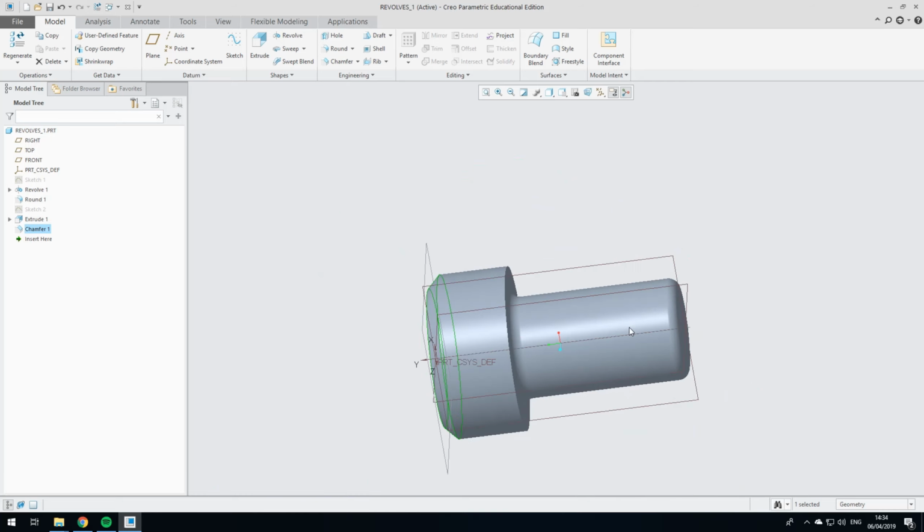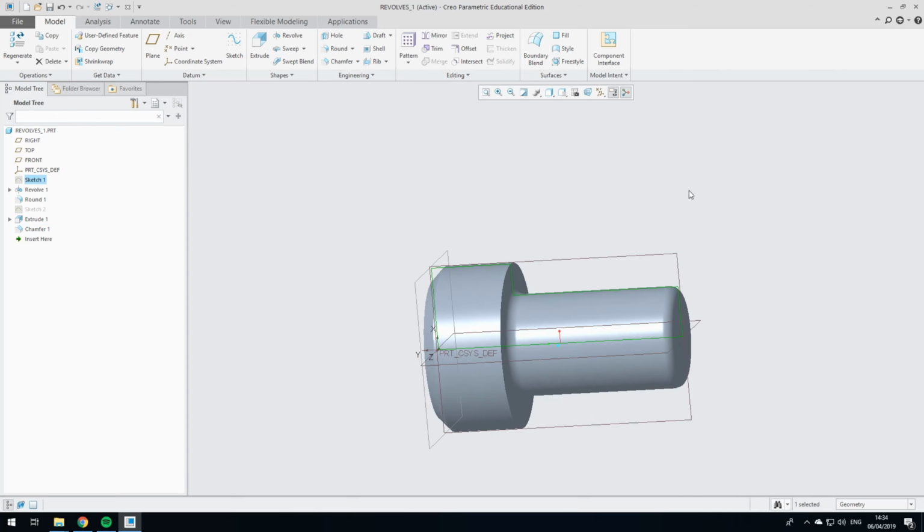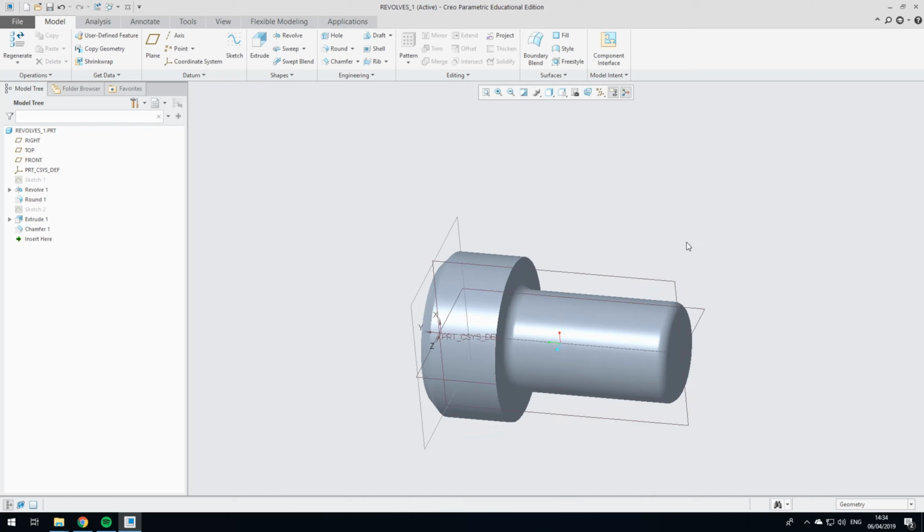Right, now the difficult part. This is what a lot of people struggle with in Creo. I have taken time over the years to learn this. We're going to add the external threads. So obviously, like I showed in the last video, if you want internal threads, like a socket or a nut, then it's very easy. You can just use the hole function, and when you do a drawing, it'll call out with the thread on it. If you did a drawing of this part right now, you wouldn't add the threads on it.